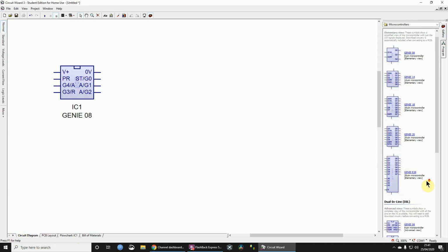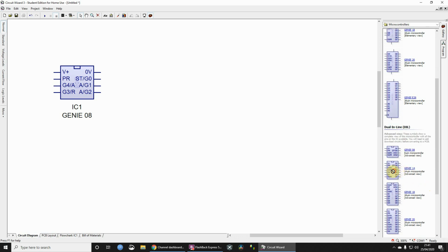But if we were to add in another microcontroller, whichever one we want, makes no difference. You'll see now there's another tabbed page, so there's a separate tabbed page for each microcontroller, and that's what you'd want. So I don't think there are many student projects that use more than one microcontroller, but occasionally we see it. And so each microcontroller would need to be programmed with its own flowchart, so that's why you have the two tabbed pages.